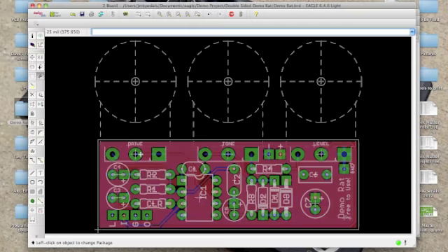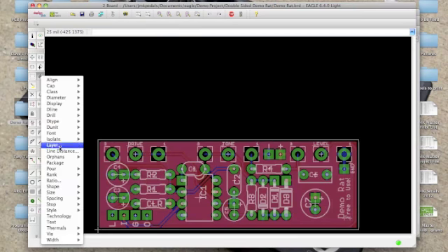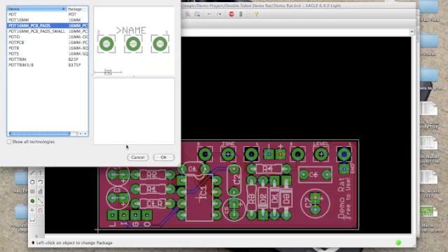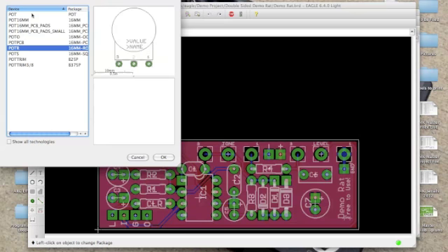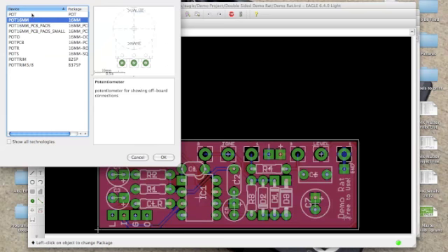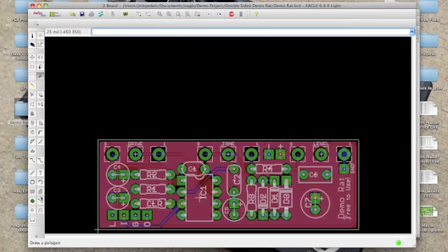Because in our old pots, let's undo a whole bunch of things here. Look at this. If I go to the package function on this pot, I have a whole bunch of different options. That's because there are multiple packages all connected to the same symbol in our device under this part. So if you want to have multiple packages, then that's what you need to do.